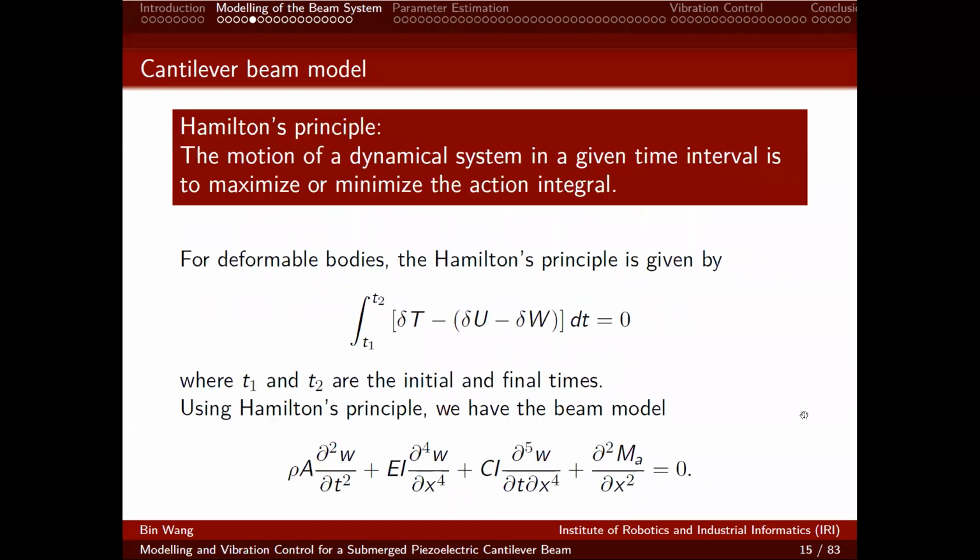With this force, we can use Hamilton's principle to develop the cantilever beam model. Hamilton's principle means the motion of a dynamic system in a given time interval is to maximize or minimize the action integral.